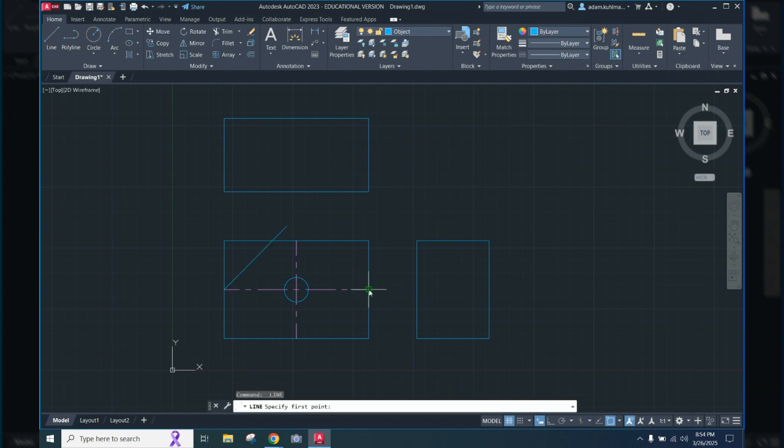And then we'll come back here. Now this time, because I've gone past 90 degrees, click twice there, this time I want my line to extend up this way at a 135-degree angle. And again, I'm just going to overshoot this on purpose. All right, so I can hit escape, and then I'll use the trim tool.